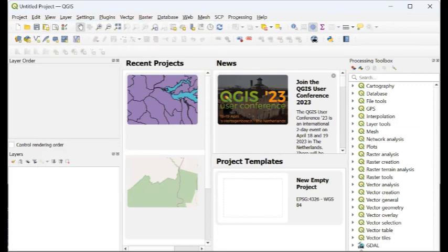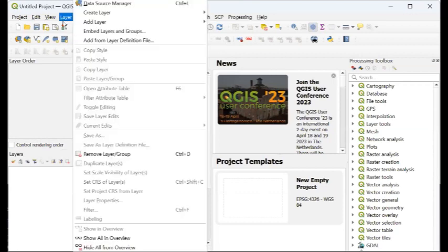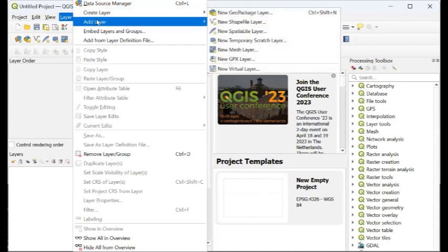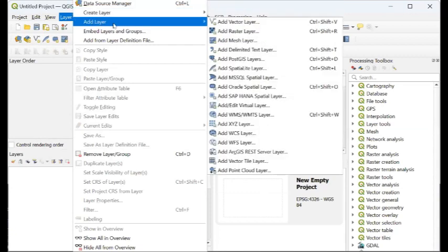So the first thing you do is, because we have given you data sets, and those data sets inside the software are referred to as layers. So you can go under layer and say you add a layer. And once you click add layer, there are a number of other tools that you work around with. So depending on the kind of layer you have, what we call vector layers.